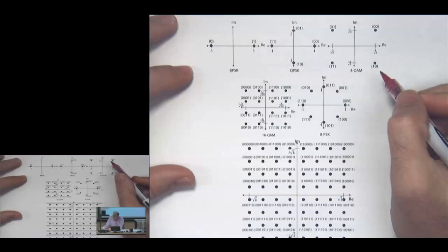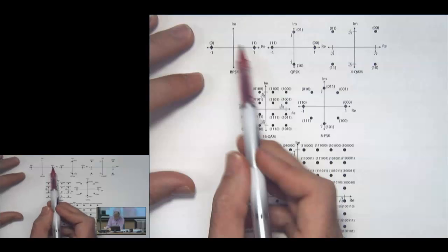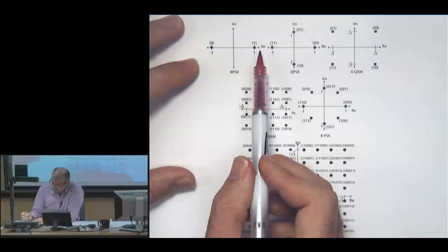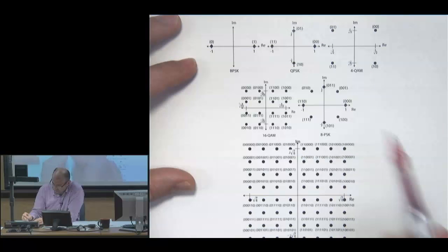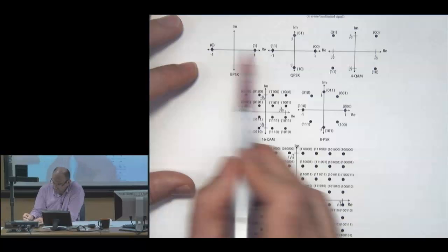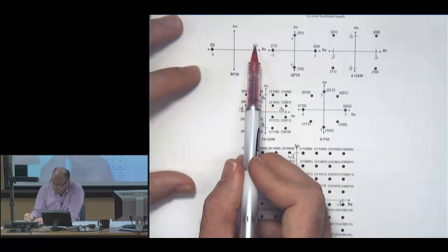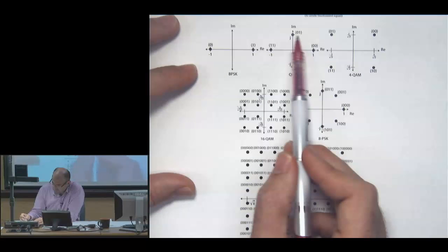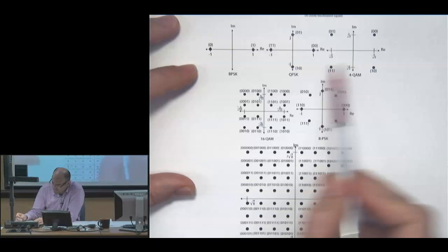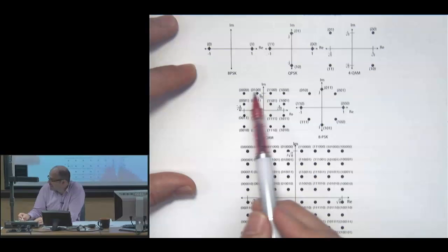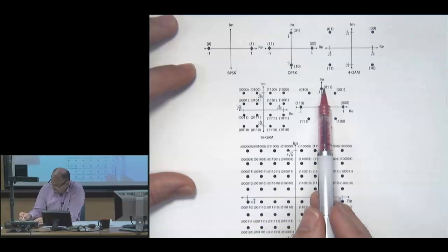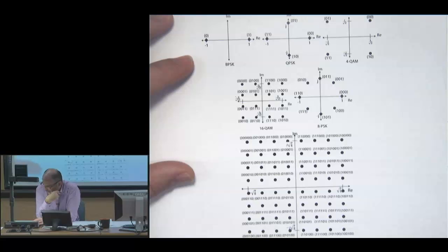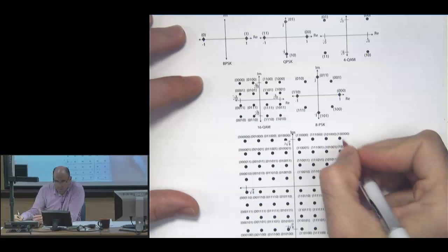So remember from Lecture 3 that each of these constellation points is associated with a sequence of bits. And when we think about digital communication systems, we label the constellations with the corresponding bits. So here, if you want to send a 1 in binary, you send 1. If you want to send a 0 in binary, you send a -1. QPSK, 00, 01, so this is 1, j, -1, -j. This is 4-QAM. And then this is 16. This is called 8PSK, phase shift keying. This is 64-QAM here. The thing to note here is that the bit labeling is done in a scientific manner, typically using what's called Gray coding.